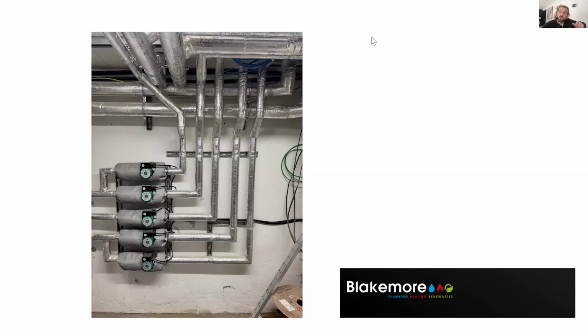I could run a fixed temperature at 65, utilize that buffer up, but I might only need 33, 34 on the secondary side. At that point, I can maximize more kilowatt hours from that buffer, and maybe I should have oversized that buffer a little bit more, maybe 1,500 litres. But that's just something that changes as we go through the job. There's nothing wrong with how it's done.